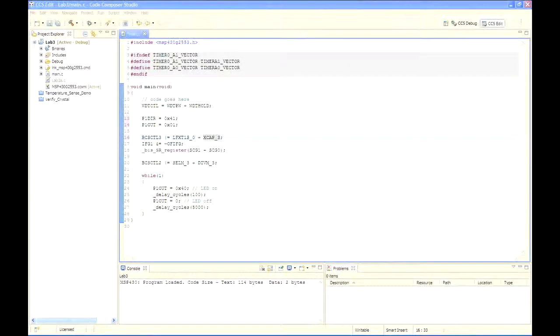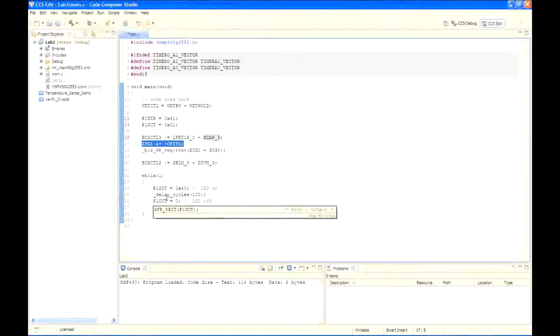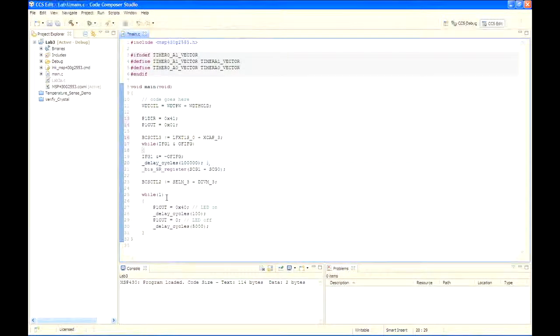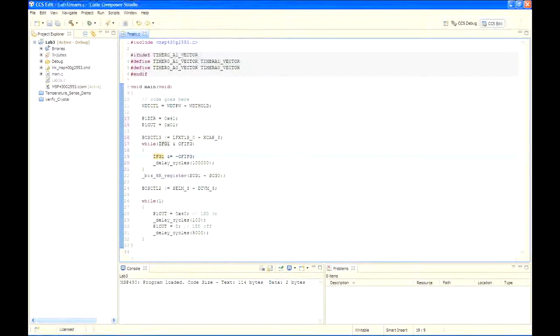In step 18, in the previous code, we cleared the oscillator fault flag and went on with our business, since the clock system is going to default to the VLO anyway. Now we want to make sure that the flag stays clear, meaning that the crystal is up and running. This requires a little loop with a test. So we're going to modify the code that simply cleared the flag, and write a little piece of code to test the flag and make sure it's cleared. Replace your flag clear with the code shown in the workbook and on the screen.